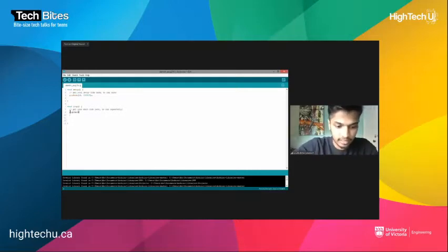I write digitalWrite pin number 13 to be HIGH. Then I wait for 1 second. The 1000 is 1000 milliseconds, that is 1 second. Then I write the same thing for off.